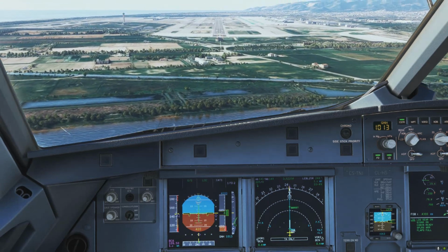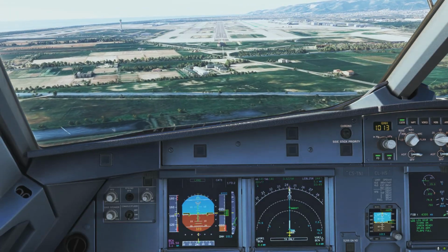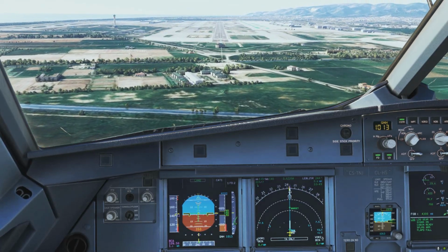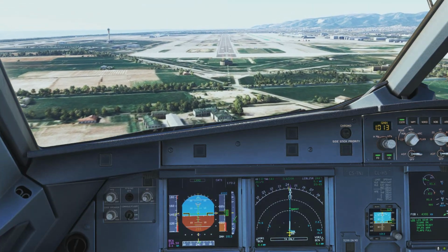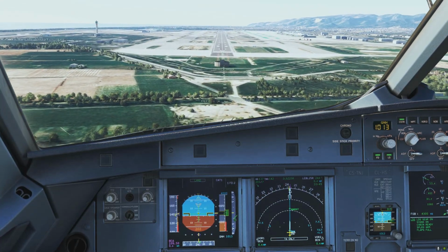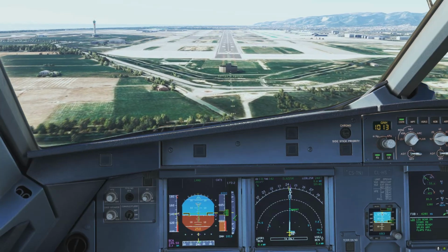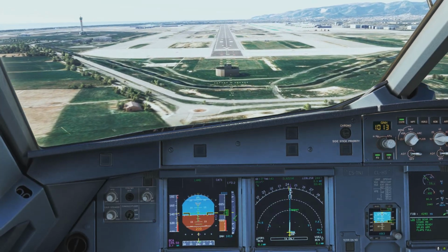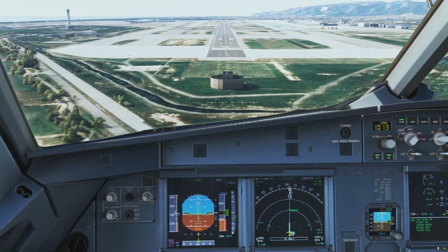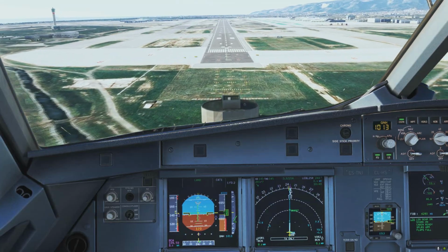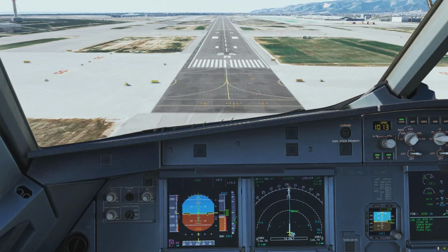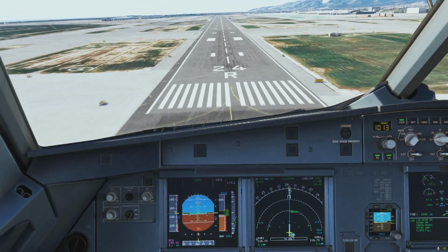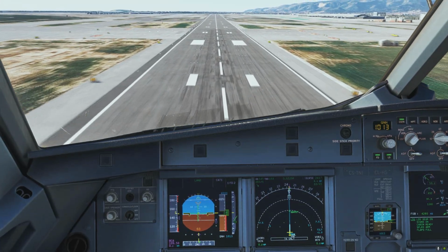Do not descend more than 1000 feet per minute at this altitude. So we're getting back on the glide. We add a bit of thrust. We're heavy, so let's give it 52, something like that, 52% and 1,200. Here we are. Still confused why sometimes the glide path does not match the PAPIs. That shouldn't be happening, but anyway.